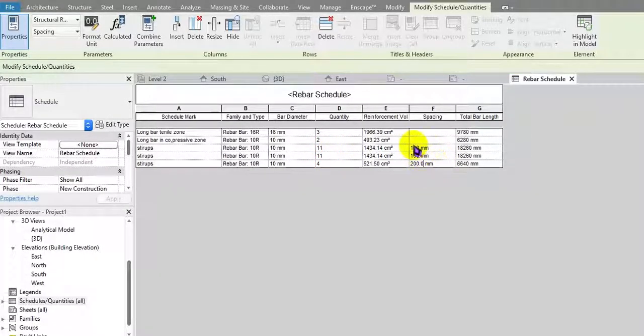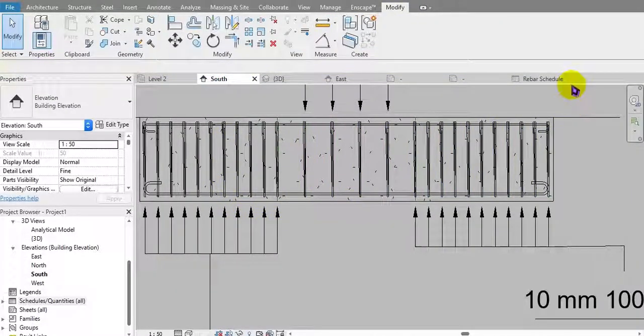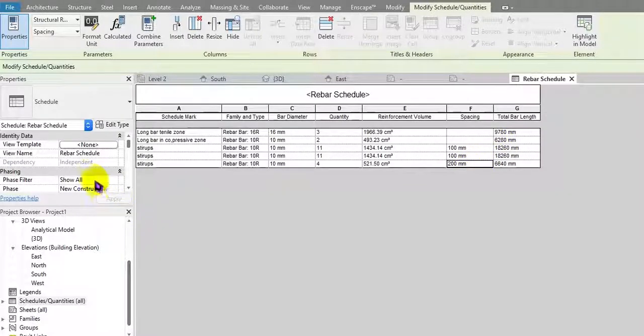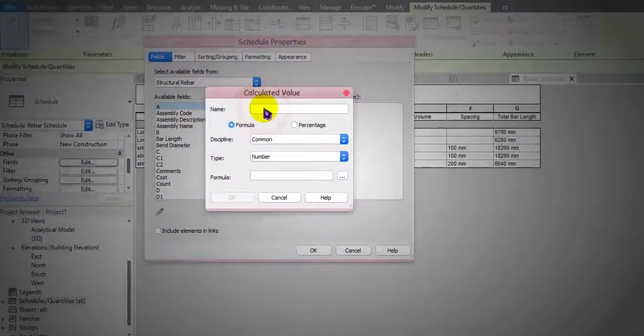also okay. So now let's try to calculate the total mass, or total weight, to be ordered in Revit Structure. So get into the schedule. I'd like to create a field and add a calculated parameter. This one will be the mass of the rebar. Mass.